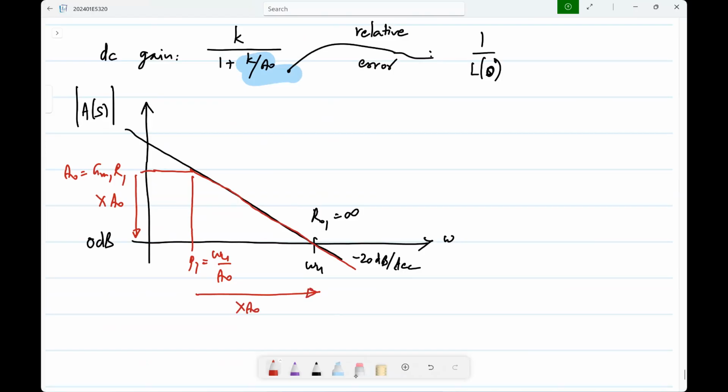And in general, in an op-amp, we don't specify P1. Okay, we specify the unity gain frequency and we specify the DC gain. You can specify any two of the three, but typically this is what is specified. Okay, because if you have a different RO1, so essentially you will get that. So that part remains exactly the same. Okay. So the behavior at these high frequencies is not affected.